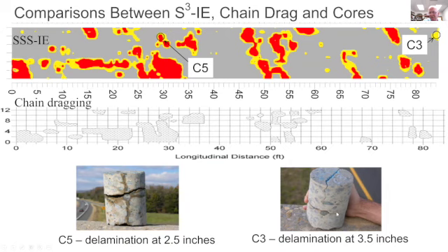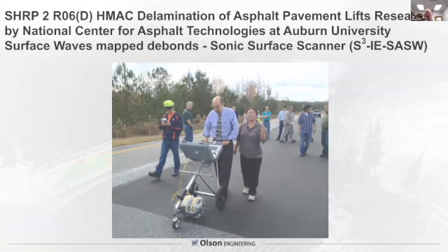And there's the steel and the horizontal crack as the steel expands approximately 6 times in volume as it rusts, causes tensile stresses and connects across the top of the deck in a horizontal crack called a delamination. And this one, everybody heard and found it. It was a core. We heard it. We found it in impact echo testing. The students heard it in chain dragging at 2.5 inches. So we kind of concluded around 3 inches is probably as deep as you can hope to audibly hear with chain dragging. So this just shows a demonstration of technology for asphalt pavements.